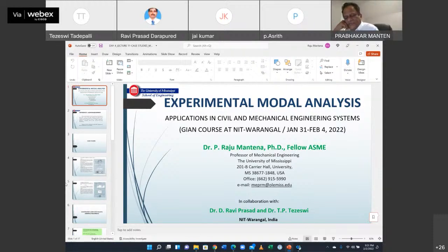Ah, yeah, I get it. For taking effective steps, what the curvature is more to do with is the strain energy associated with the curvature, right? So if I'm applying damping treatments, I would like to apply them at those portions where that curvature exists rather than at the tip of a sample where there is no curvature, where there's no strain energy. So maybe you're referring to that.